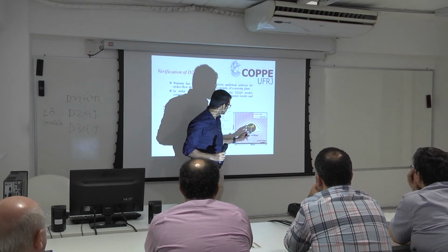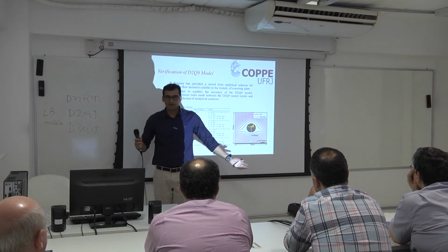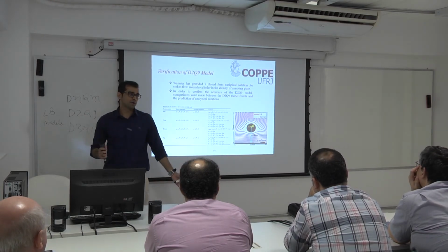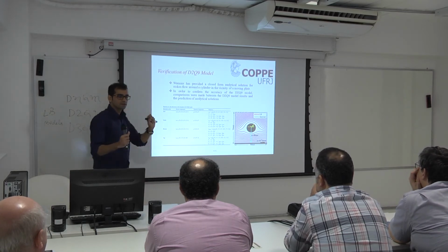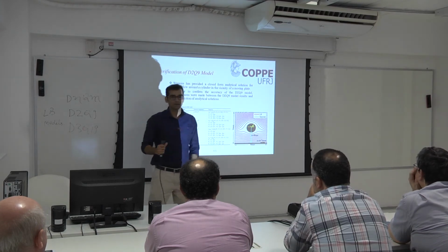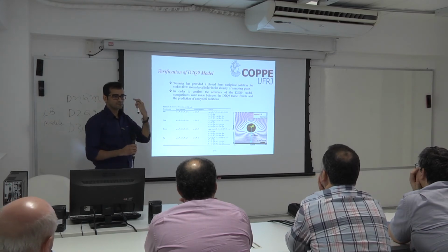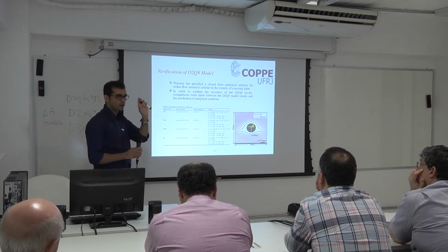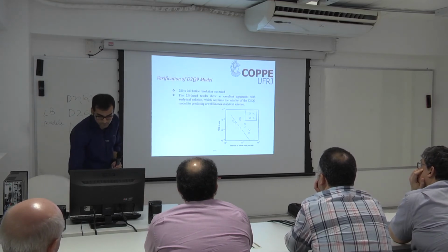You see the lattice Boltzmann and the Wannier results are hugely in agreement with the analytical solution. But the only difference was that the geometry that he used, D2Q9, was rather simpler. He didn't incorporate the complex geometry of porous media like carbonates in this case. Anyway, we will do that.